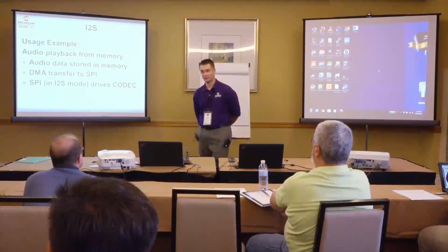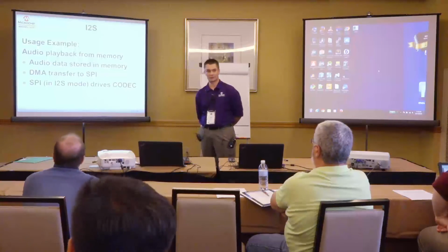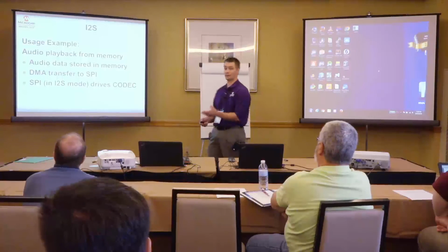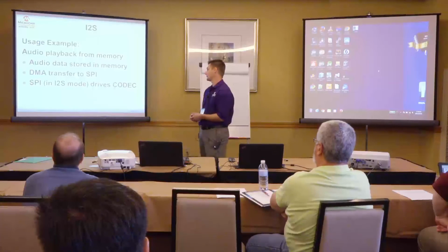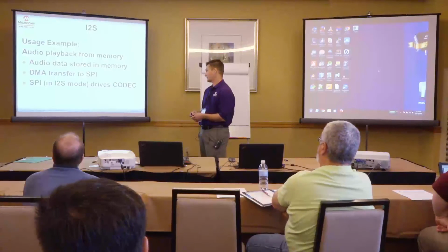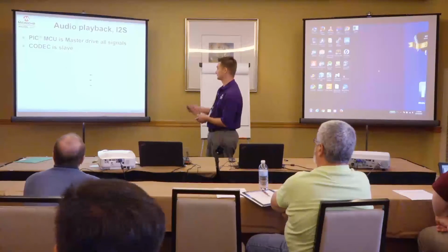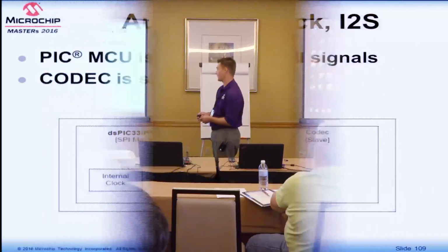Like, how can we leverage these peripherals to work by themselves so your code can do something else or nothing? You can put it in sleep. So here we have the SPI in I2S mode and hooked up driving a codec. So quick block diagram of what that looked like.